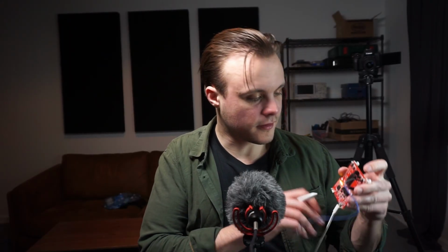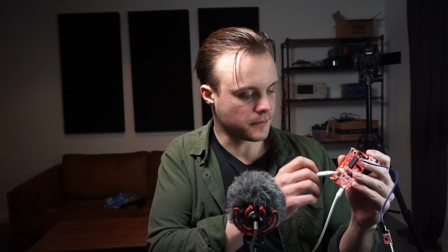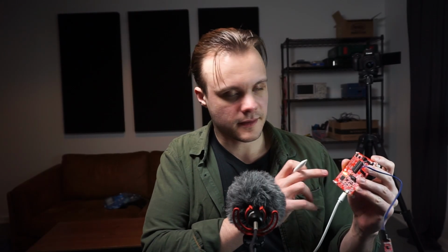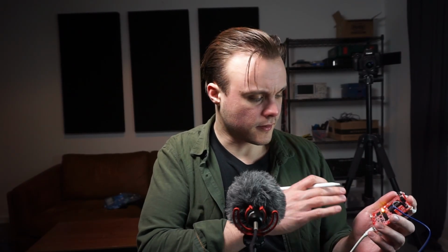In this case, it's not strictly necessary for me to have this separate chip, since this development board actually has a separate USB-to-UART chip on it. But since it's limited in terms of how high a baud rate it can use, it only goes up to 9600, because it has been pre-configured that way by TI, and I don't think there is an easy way to change it.